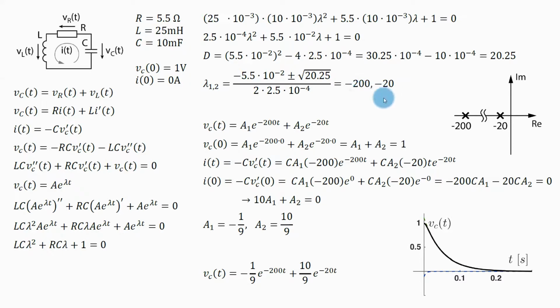With two different roots, the general solution of my differential equation will have this form. I have already substituted for the lambdas. And now I will continue in the same manner as before. This is my general solution, so this describes all the behavior of my circuit. I want to have one behavior which starts with these initial conditions, so I will need to use those initial conditions. First, this one, I will express the general solution at time 0, which is this, which gives me this, and that is supposed to be equal to 1 because of this initial condition.